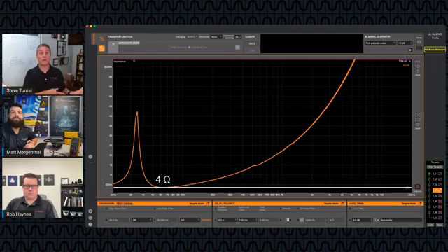And it's not an issue for your amplifier because it's intended to drive an AC load, no problem at all. It's just an abnormality when using DC resistance on your meter to try to figure out something that's really an AC intended circuit. Does that make sense?